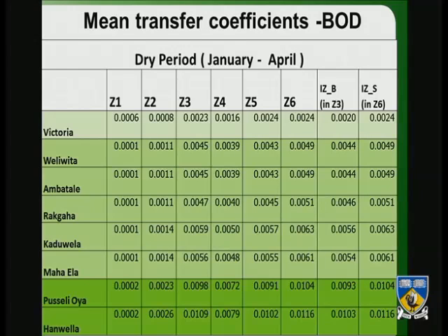So the biggest problem is that people don't comply with the limits that the government has set. Is that the main problem? That is also a main problem. So the main strategy would be to have more monitoring? Yeah, that was the idea. The Central Environmental Authority is trying to monitor, but they have limited resources and it is difficult to monitor. What I see is that monitoring individual industries was the idea, but industrial zones make more problems than individual industries. Because if they increase just 10 milligrams of their BOD, you will have 150 kilograms per day of pollution load. It is only 2 zones, so closely monitoring them is more important than just going after small industries.